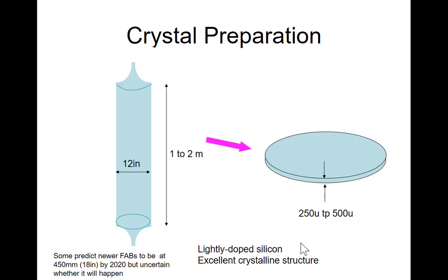What you do is after you have this ingot, you put it sideways, and as you are turning the ingot, you put an RF coil around it to heat it up, and you go across the ingot, and then you cool down at the same temperature. Now it becomes more uniform, and the stress becomes more removed.